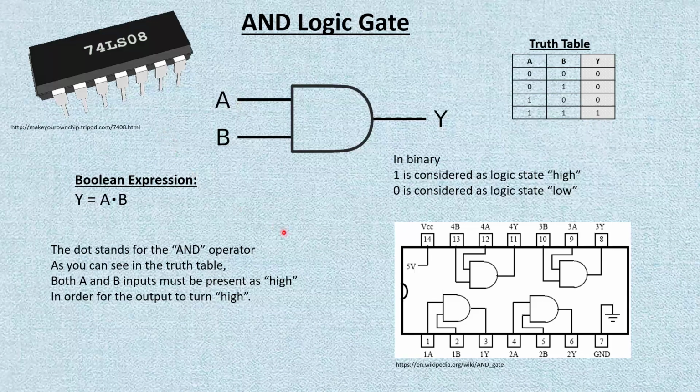There's going to be a range of voltages from 0 to 2 point something, and then 3 to 5, which is going to be considered as 1. That's for the inputs, and for the outputs, the table is also going to show you what it is actually going to guarantee you on the output, between what and what is considered as 1, and what voltage is considered as 0.